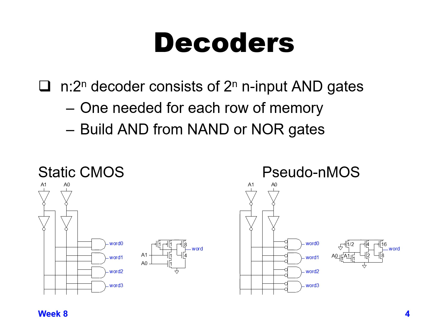One with static CMOS, where we have A0 and A1. We're generating A0, A0 NOT, A1, A1 NOT, and then we tap off from the appropriate combination. There's 4 different permutations of tapping off from those that we can get to then decode word 0, 1, 2, and 3. The AND function is a NAND function followed by an inverter.